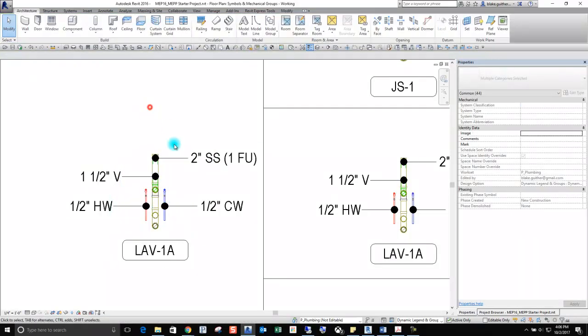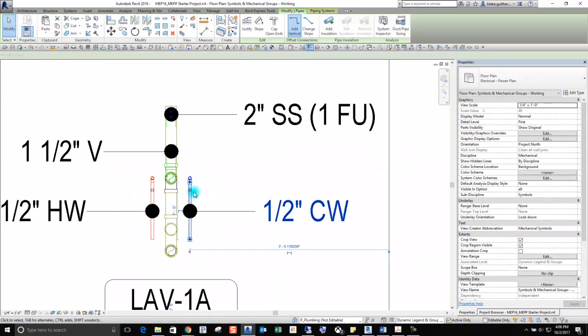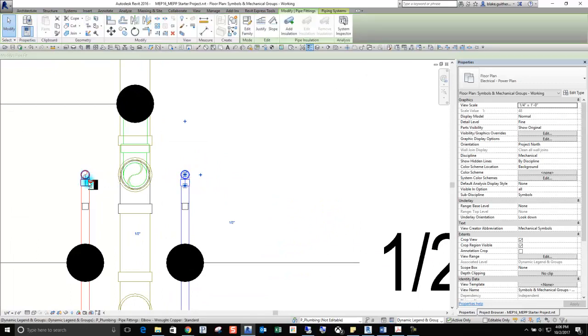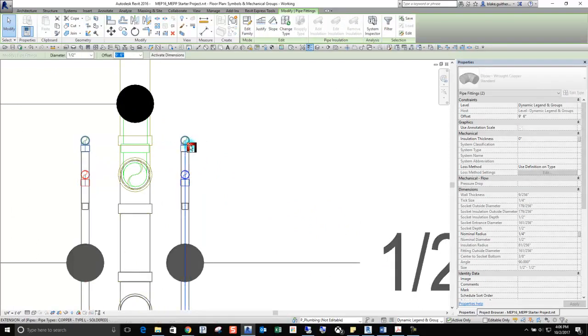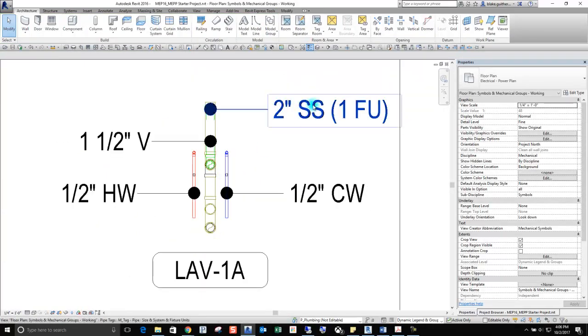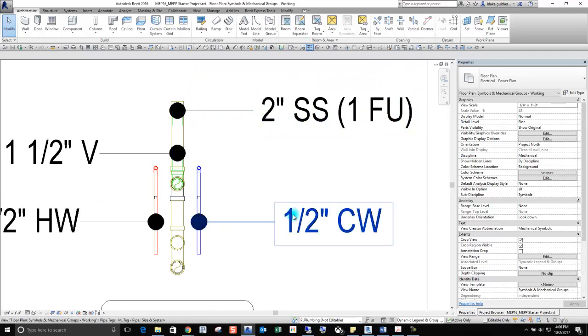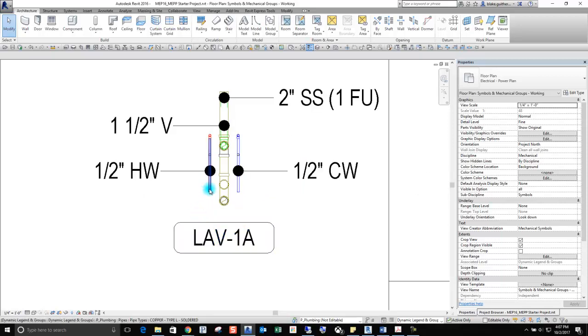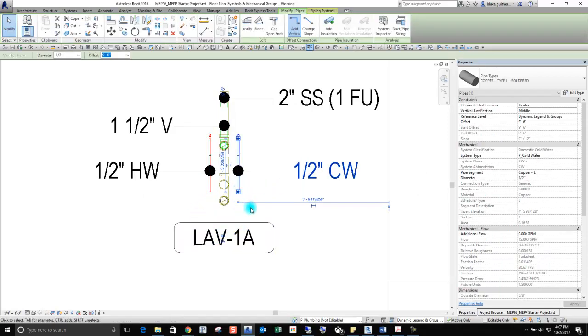you ungroup it, and now it's entirely live. So now you can move these elements wherever you needed to. So if you needed to move these elbows in or out further, now it's all freeform, everything's connected. The reason we put these tags on here is to show you guys that there truly is connected fixture units throughout, which, you know, all that tedious detailing work and connections have been done once, and you just have to place the group. So now you've got connections here that may tie into, you know, mains running across in a ceiling. So you'll see some more of that in the next video.